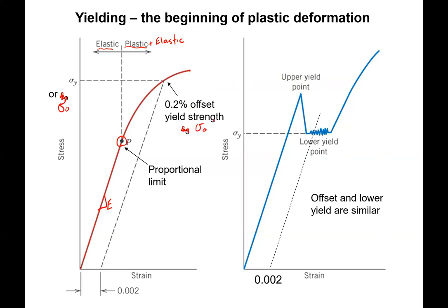All right. So this yield strength is defined by, on the strain axis, moving over to 0.002 in strain, right, 0.2%. And at that point, we go ahead and we draw a line with the slope of the elastic modulus. And then where that line hits our stress strain curve, that is our yield strength value. So that's the method that we would use to find that.